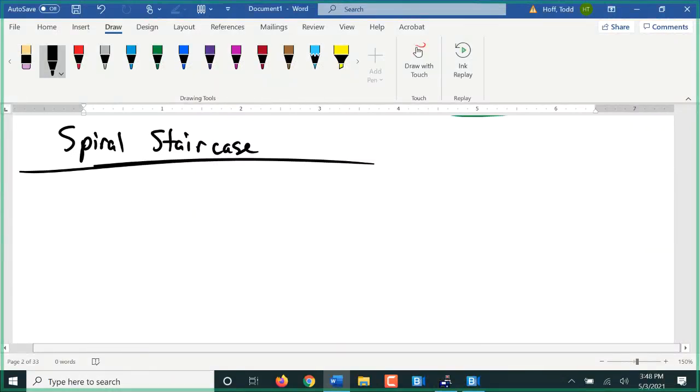Well, this is saying 8 1/4 inches, but I don't think that. I think you can still go 9. OSHA for industrial standards, I think is like 9.5 actually for equipment. Equipment and furniture? Well, that's for like catwalks and stuff for an industrial.